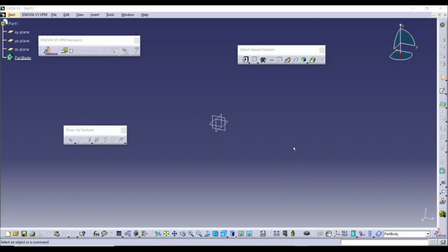In the previous lecture, we showed how we can use a tool pad. With tool pad, we can add material by converting a two-dimensional profile to a 3D feature. Now we're going to show a tool pocket. With tool pocket, we can remove material from the geometry by extruding a sketch. So first, let's create a new 3D model.